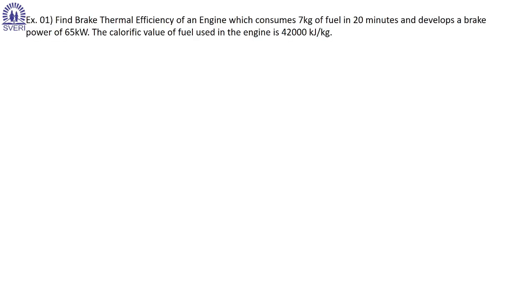So first problem: find brake thermal efficiency of an engine which consumes 7 kg of fuel in 20 minutes and develops a brake power of 65 kilowatt. The calorific value of fuel used in the engine is 42,000. So what it is basically asking is to calculate a brake thermal efficiency.